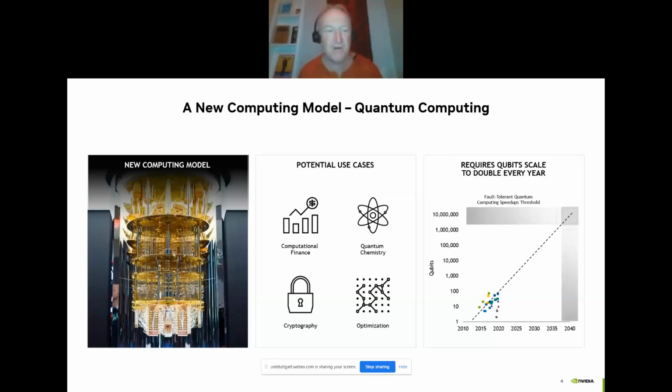So this picture we're showing here on the left is a common picture you've probably seen when we talk about quantum computers. Everyone likes to show this picture. It's rather beautiful. The vast majority of what you're seeing in that image is not the actual quantum computer. It's this little device in the very bottom here, the actual Sycamore processor. This is Google's quantum computer, and everything you see here is the refrigeration unit. This is a superconducting approach to creating quantum computing, and it's largely about bringing the temperature to near zero for the superconductors to operate. So almost everything you see here is part of the refrigeration unit with the quantum device there.